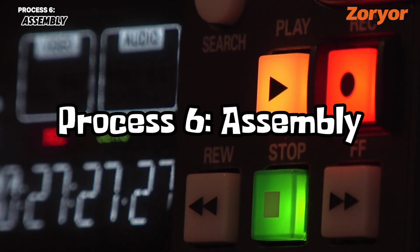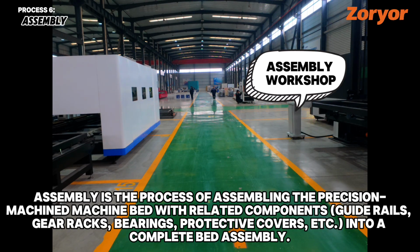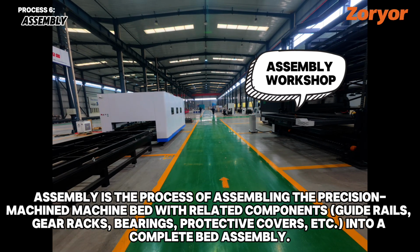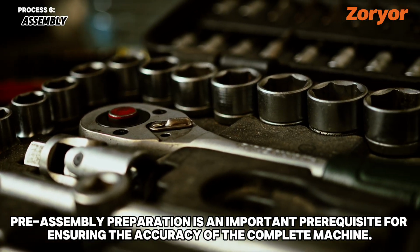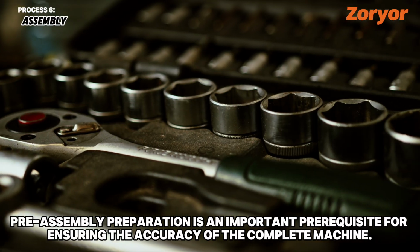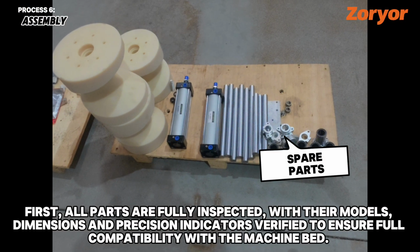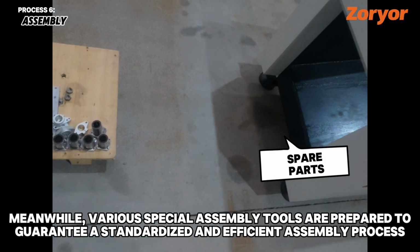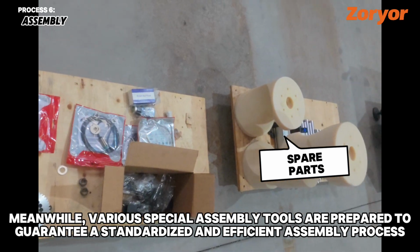Process 6. Assembly. Assembly is the process of assembling the precision machine bed with related components, guide rails, gear racks, bearings, protective covers, etc., into a complete bed assembly. Pre-assembly preparation is an important prerequisite for ensuring the accuracy of the complete machine. First, all parts are fully inspected, with their models, dimensions, and precision indicators verified to ensure full compatibility with the machine bed. Meanwhile, various special assembly tools are prepared to guarantee a standardized and efficient assembly process.